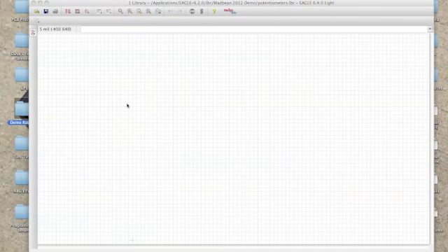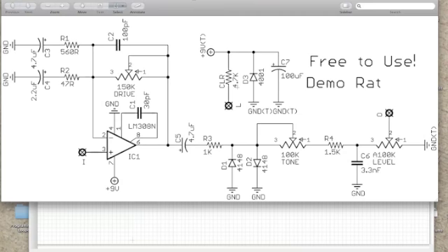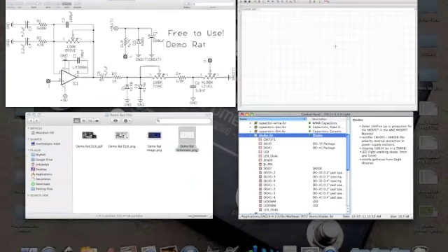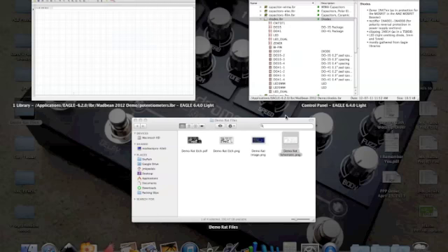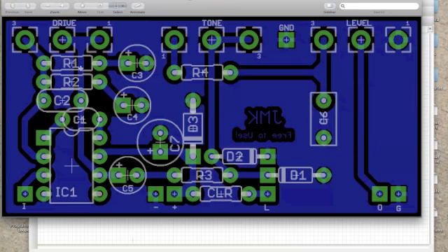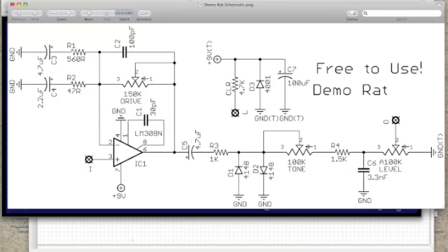When you look at your schematic, these symbols are the elements of the device that correspond with your symbol options. The package is the part of the device that corresponds with what you see on your layout. So this is the R1 package, and this is the R1 symbol.